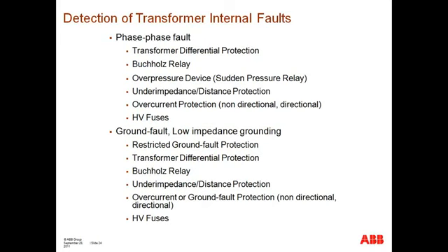Essentially, a Buchholz relay is a mechanical device. Usually when faults occur, there's a breakdown of the oil inside of the transformer, and that breakdown of the oil results in gases being released. This device is essentially a floater type: when this breakdown of oil and release of gas occurs, that gas is going to come up to the surface of the level of oil, and this device is monitoring for those bubbles coming up. If the flow of the oil is severe enough, it's an indication that gas has been released within the tank, indicating that a problem has occurred within the transformer.